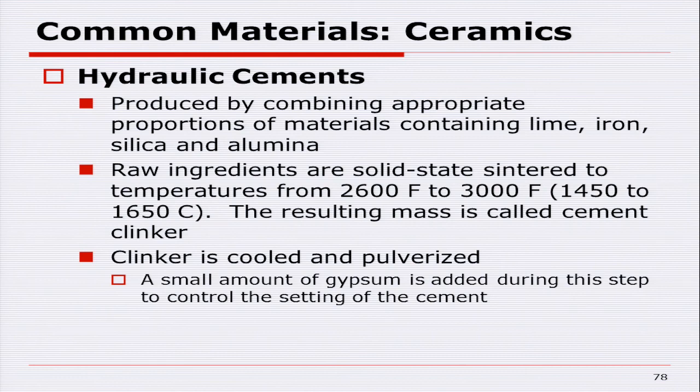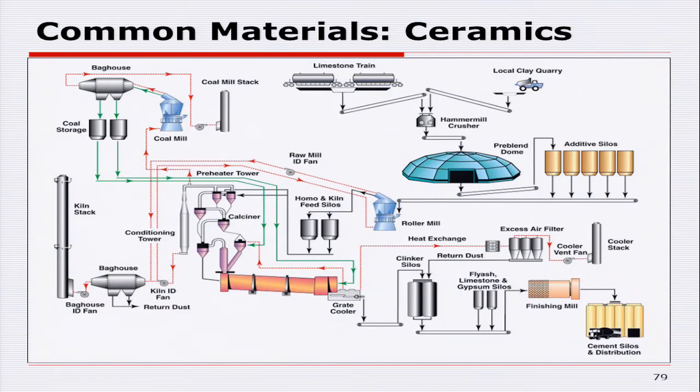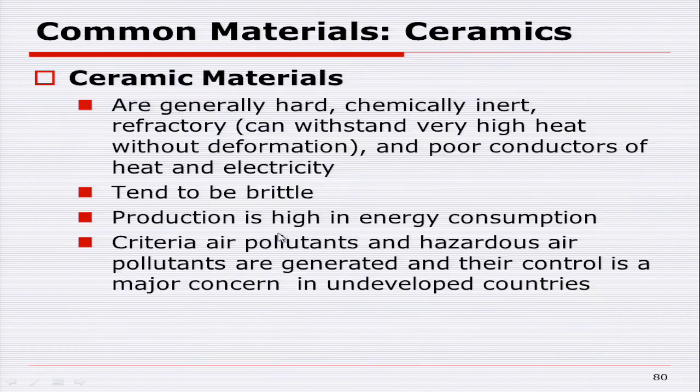If you don't do that and you try to put it in a kiln and heat it up right away, you'll just blow your pot apart. All that water and air turn to steam and just blow stuff apart. So you need to slowly let that water vaporize and move out of that mass. And you're also driving off other things, carbon dioxide and some other things that will oxidize at that lower temperature prior to sintering. This just shows a shot of a batching plant for